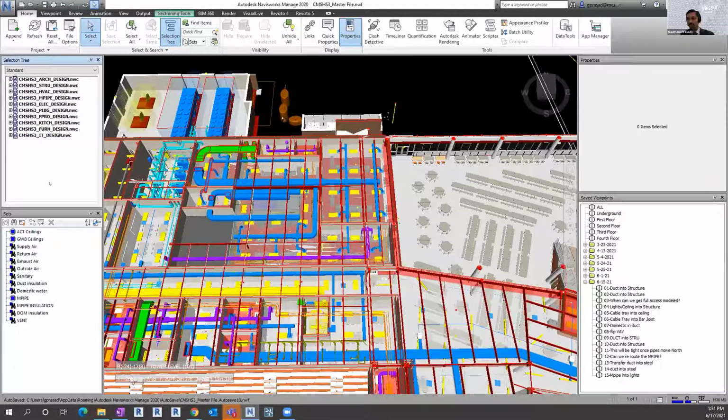Okay, so as Heather mentioned, CMS, Charlotte-Mecklenburg Schools, has a pretty robust BIM standard. Some of it doesn't make a ton of sense. They ask for a clash detection log, which has fields for at a minimum clash number, clash location, column line intersection, trades involved, recommended solution, and they want you to do that for every clash, which could be thousands. So I said, gosh, guys, can we do this another way? And eventually we got them to what we're doing now.